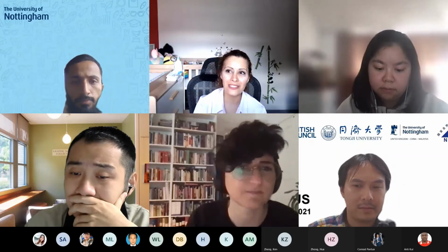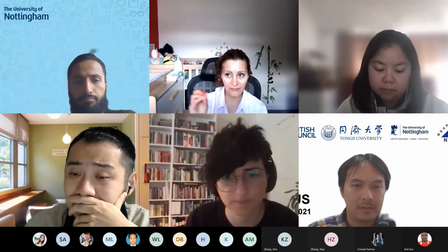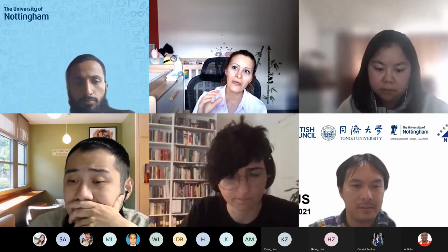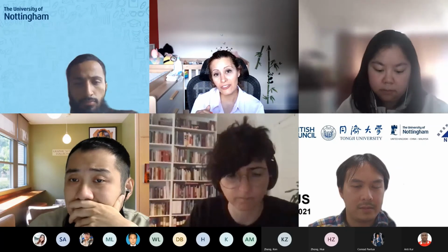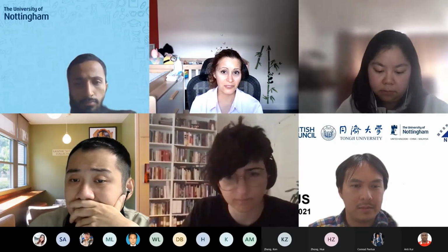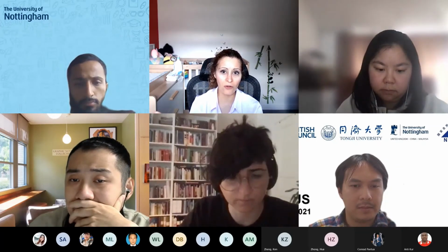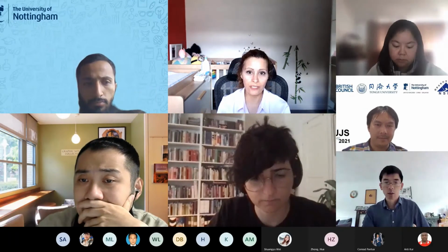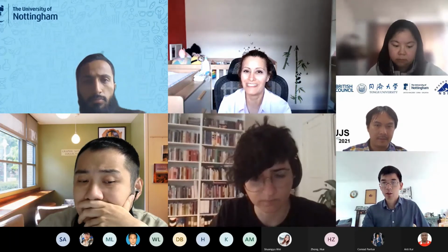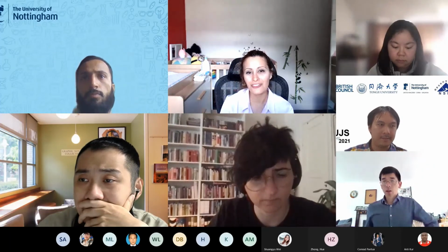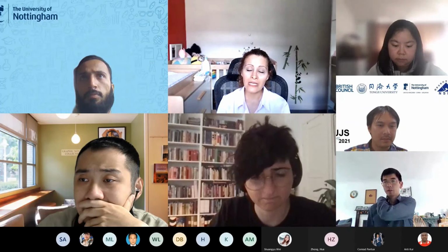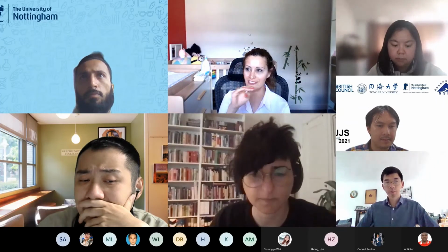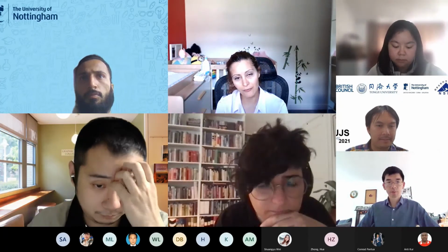Why? Because specifically if you're closer to that equator, then you're not having enough day and night temperature changes. So many strategies already go out of the window. Such as thermal mass. It is too humid, so evaporative cooling is out of the window. So a lot of very good strategies go out of the window, and also there are not much seasonal differences either. So the temperature is kind of 30 degrees all year round, more or less, depending on where you are.